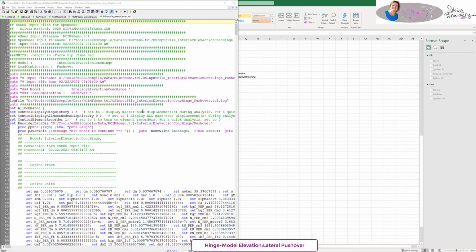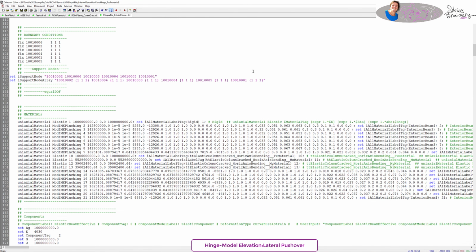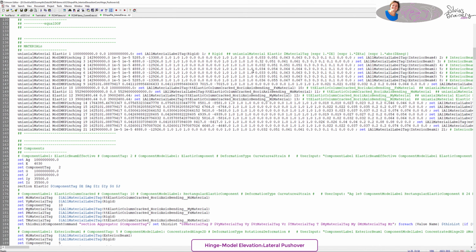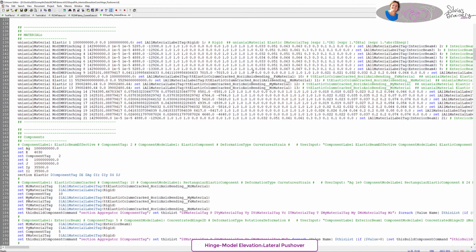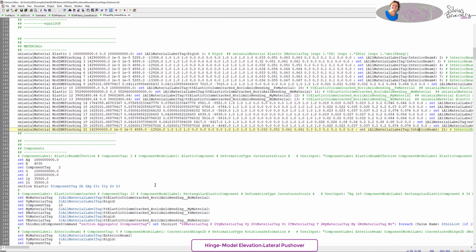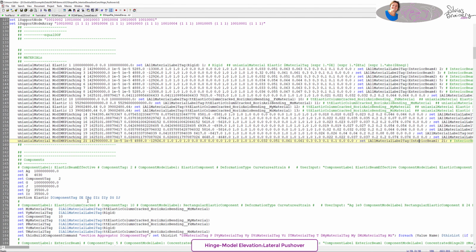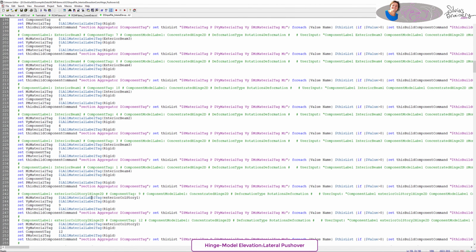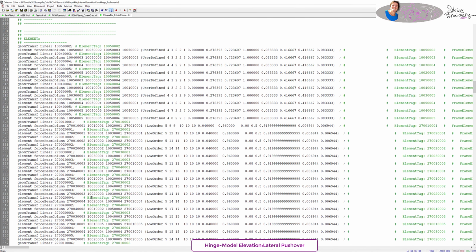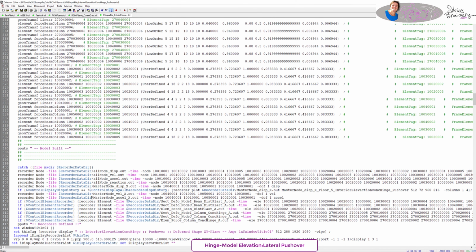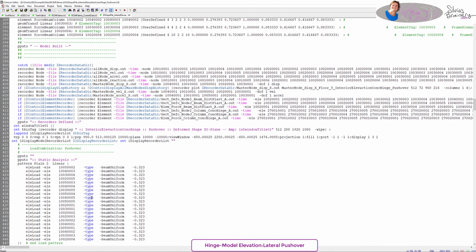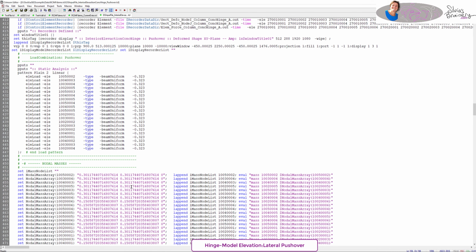Well, one way to stiffen it is, maybe they didn't use the cracked section in the column, maybe they used the actual section. And what I'm finding out here is, for example, I'm looking at the OpenSees property and the input, and I noticed here, I think, is where I realized that, hey, I was using a distributed plasticity condition when I should have used a concentrated plasticity condition.